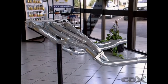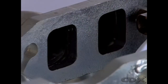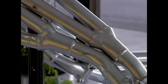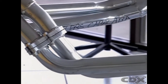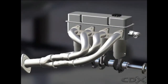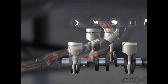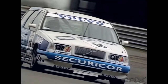Some exhaust systems have extractor pipes, sometimes called headers, one pipe for each exhaust port. They are designed with sweeps that stop restriction. The extractor pipes also provide a scavenging effect, helping remove exhaust gases from the cylinders. The outgoing pulse from one cylinder is timed to arrive at the junction at exactly the right time to help draw out the pulse from another cylinder. They are widely used on high-performance vehicles.